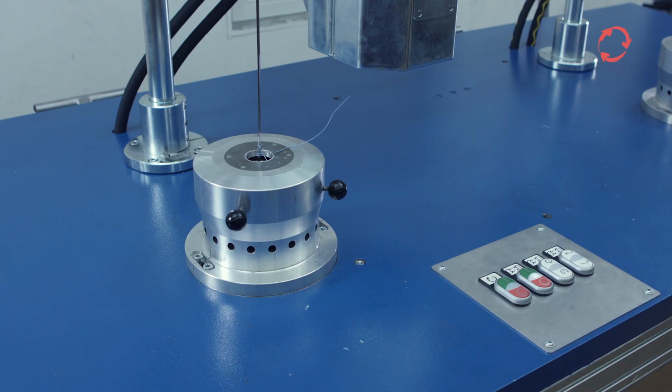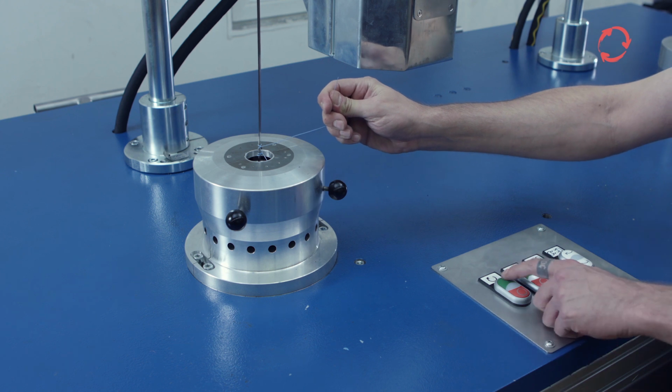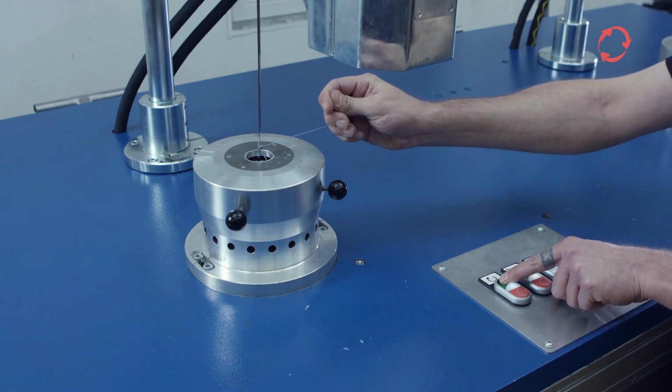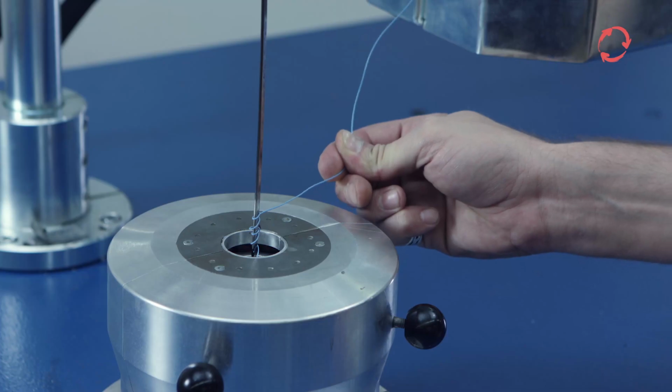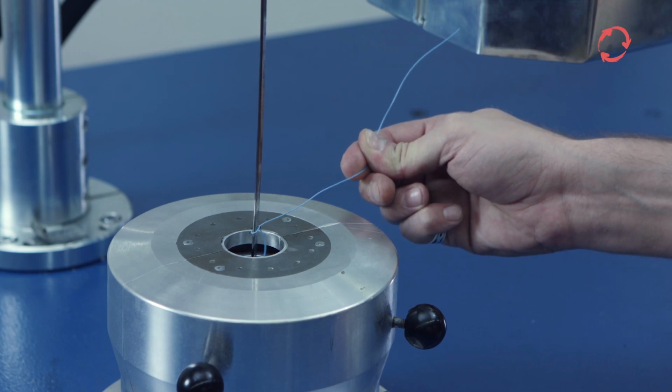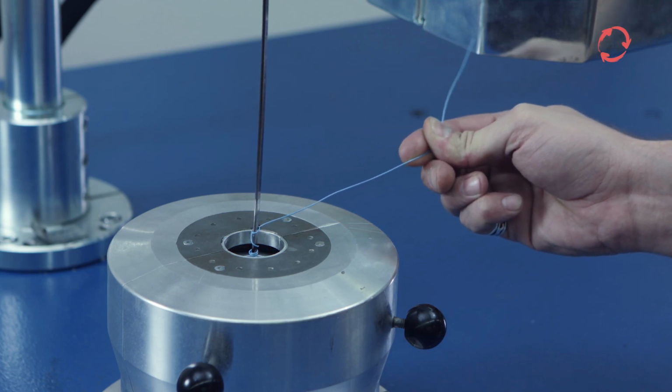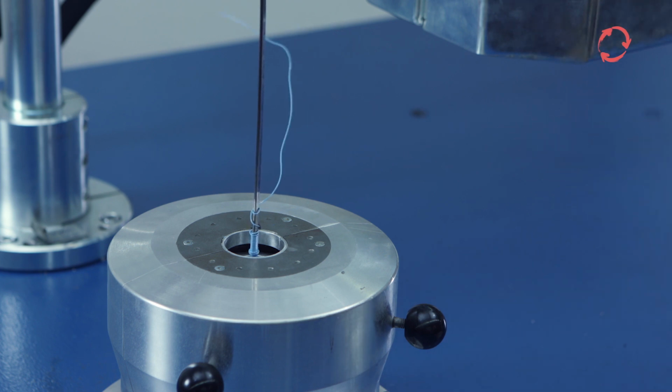Once the heater has reached the target value, see window Actual Value, the spindle can be started by pressing the green Start button on the top of the machine. When the spindle starts running, the tied spiral wire must be secured with 2 fingers during the first rotation to prevent it from winding onto the mandrel.